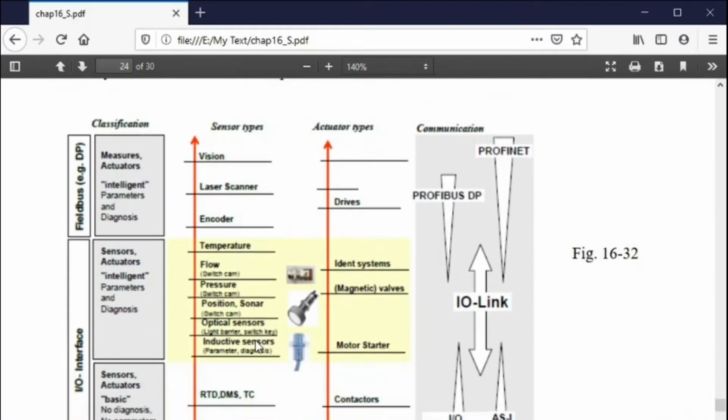There are other networks other than Profinet and Ethernet IP. So we talked about Devicenet up there before. Now this is the European version, and you can have straight digital I/O, or you can have what they have now, which is called ASi. And ASi is an equivalent of Devicenet, although it works at a higher speed. So Devicenet, while it may have kind of gone away, is not totally gone away, and the competitive one is ASi, A-S-I. It's said as "Asi".